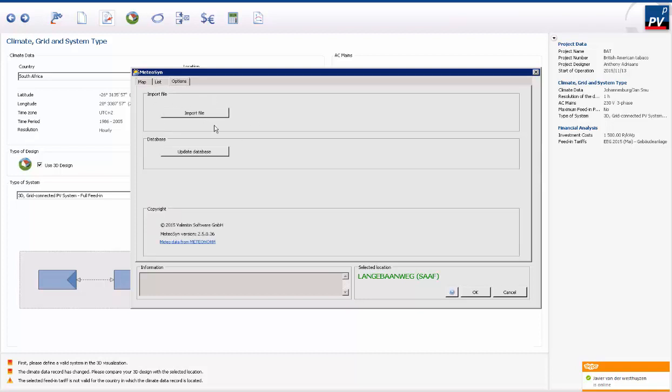And if you have climate data which somebody else has already done, let's say you've got a company to go out and do climate data for you, they can make the file and then you can import it. From Meteonorm, typically, though not from Meteonorm only. Meteonorm has a certain file format, so you can send the data of your weather station to Meteonorm, and they can make you a file which you can then import.